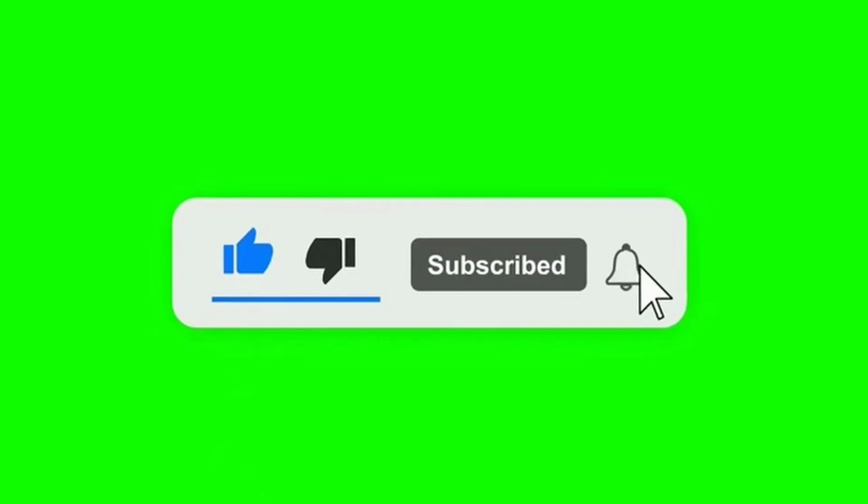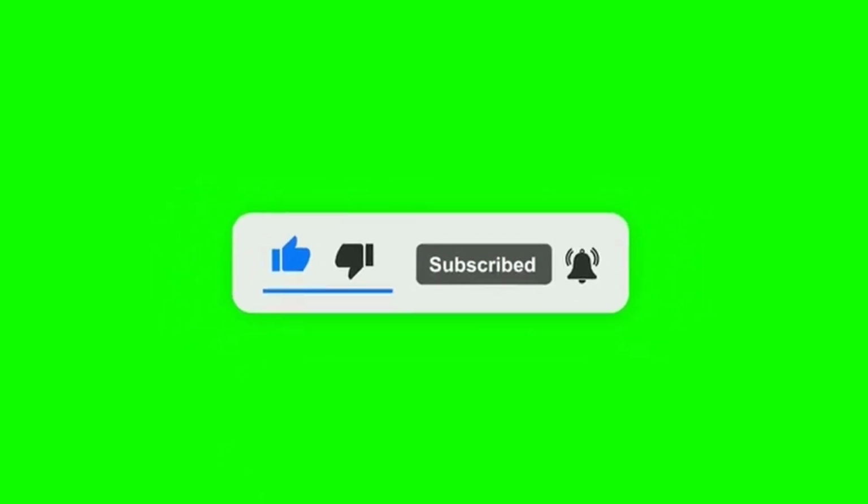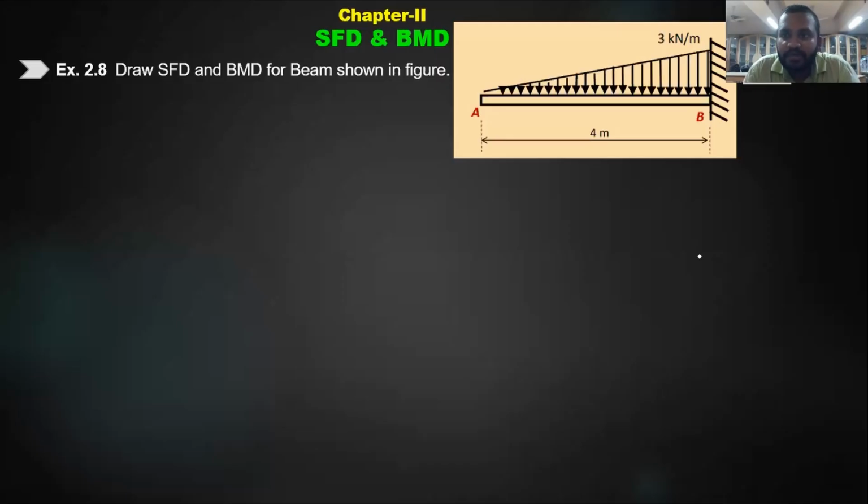In the last lecture, we discussed what is shear force, what is bending moment, and how we draw SFD and BMD for different applications. So again, we have another numerical on the same lines. We have a cantilever beam which is having a UVL. The end B is fixed and end A is free, and the span is 4 meter and the maximum intensity of the UVL is 3 kilonewton per meter.